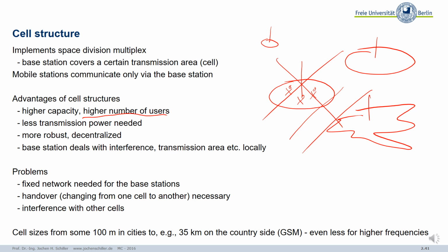If you drop out of a cell, you can automatically be handed over to an umbrella cell with a stronger, larger antenna and more transmit power, but less overall capacity. You cannot handle the whole town with one umbrella cell, but you can handle all those subscribers dropping out of a smaller cell before they re-enter another cell.